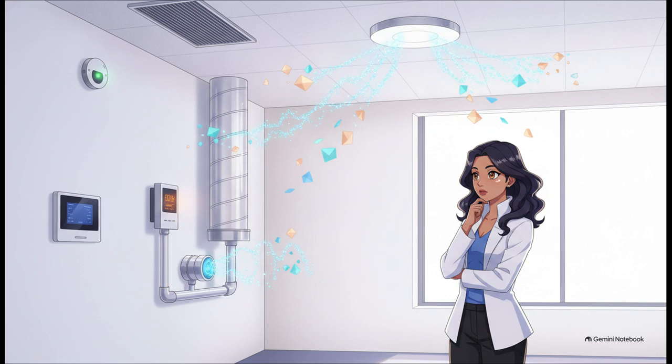We've got sensors feeling the temperature and humidity in the offices. Others are sniffing out CO2 and measuring airflow in the ducts. You've got pressure sensors checking if filters are clogged, occupancy sensors to see if someone's actually in a room, and flow meters tracking water and energy. They're constantly generating the raw data the building needs to essentially feel its own state.